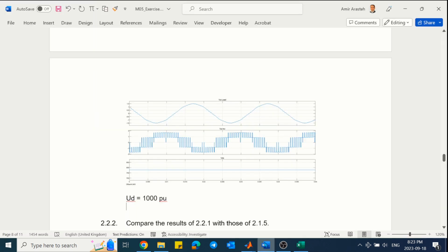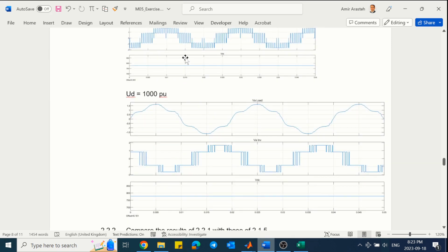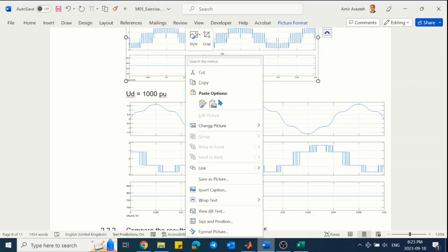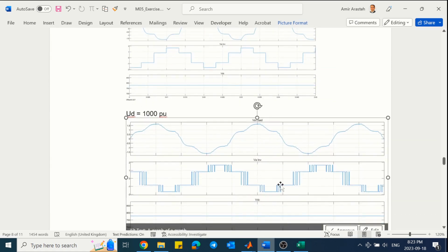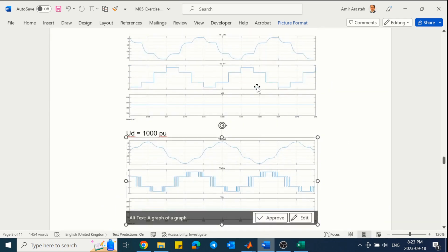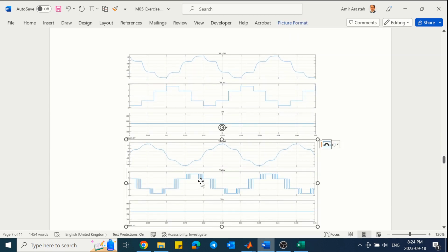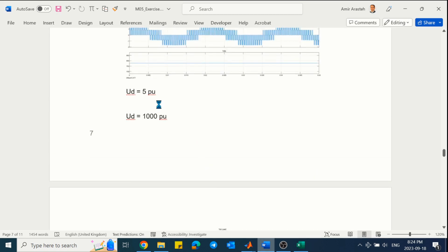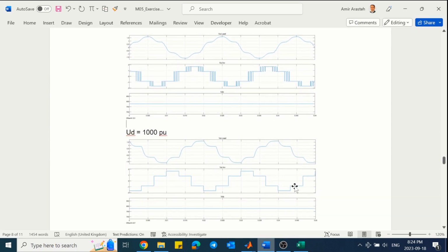The previous one, yes, sometimes there are some delays when copying the data of a scope to the clipboard. So here we could see that there was a delay. If you are facing this problem, I recommend that you wait a bit after copying the data so it is actually loaded into your clipboard, and when you paste it, you will have the correct graph.